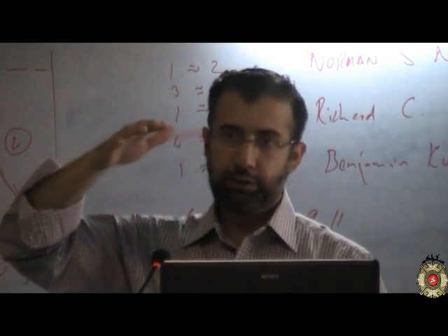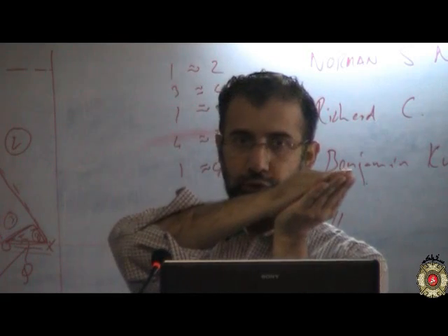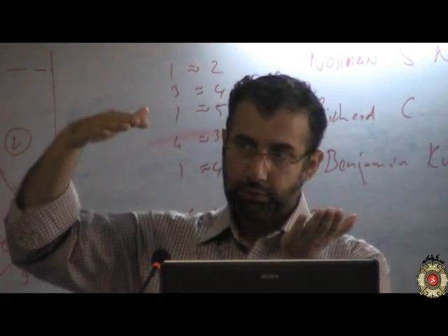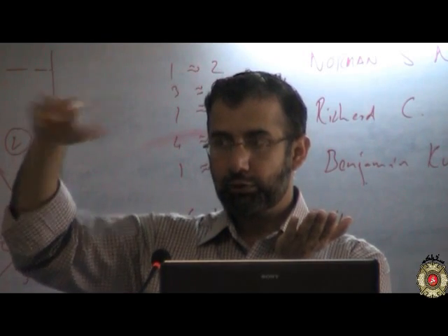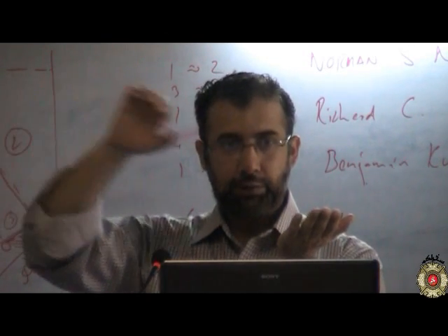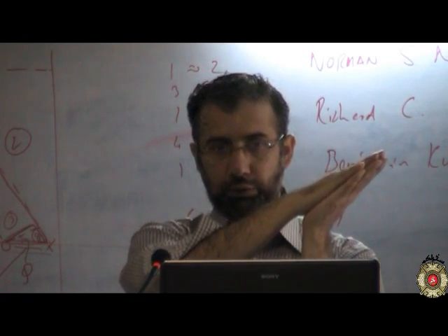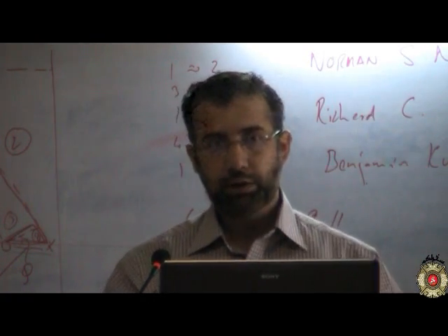altitude, because they have a diaphragm which has, let's say, atmospheric pressure enclosed, and then you have an outlet which is the physical pressure at what altitude it is flying. So it measures that pressure, and it knows the atmospheric pressure in that diaphragm, so that expands or closes, and the meter kind of moves, which tells you how high you are in altitude.